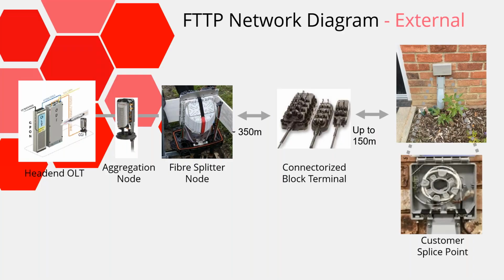ODF cabling with OLT, which stands for optical line termination, is held in the exchange together with one more WDM, which stands for wave division multiplexer, which is just a filter, mixing and unmixing connections, right? So they leave the exchange and typically go underground to connect to one of the CCJs, cable chamber joints. Here, Openreach will have different types of cables connected, usually yellow, black, and white.